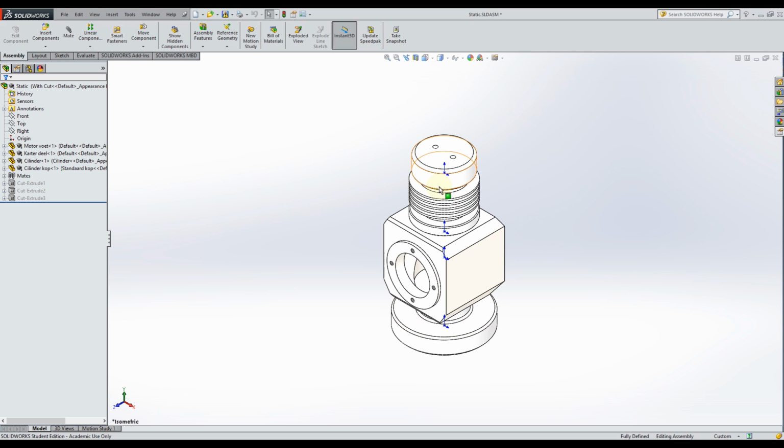So if you have a moving engine, then for instance your crankshaft cannot be your first primary part, because that would mean that all the other remaining bits of the engine should move around the crankshaft, which is normally not the case. So in this case our static engine assembly, which won't move, has our main part, and our crankshaft moves within our static part.